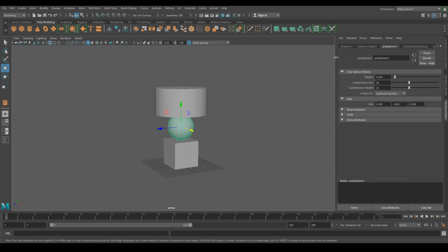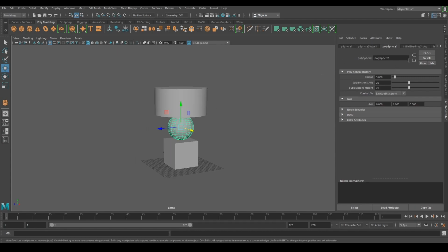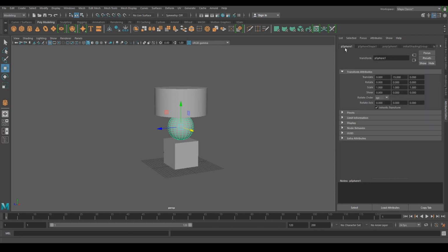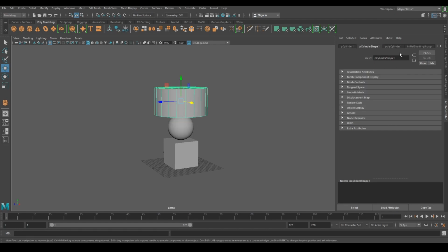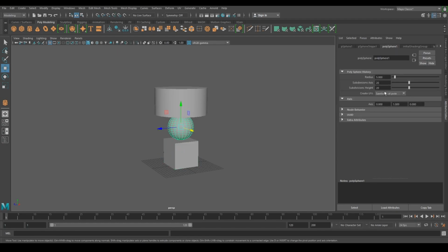And also, this is good to know, you can actually expand this, but sometimes if it's too small, you'll see a little arrow next to that, and you can actually scroll along, particularly when we start dealing with colors. Okay, I'm just going to leave it there. So the first tab is the position in 3D space. The third tab are the parameters for the objects, and they're different depending on the type of object it is. So if I go to the polycube, it gives the height, depth, and width. For the sphere, it gives the radius.